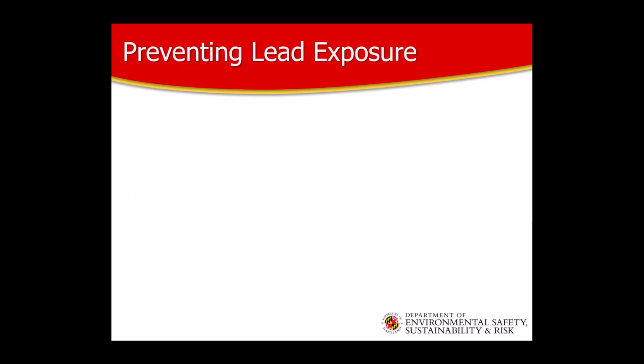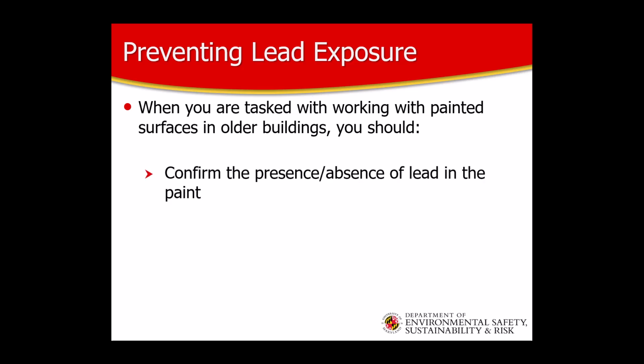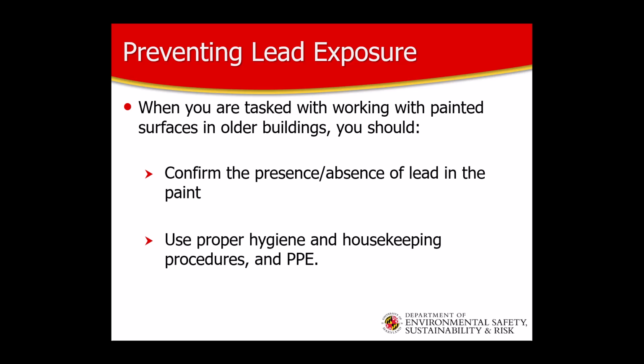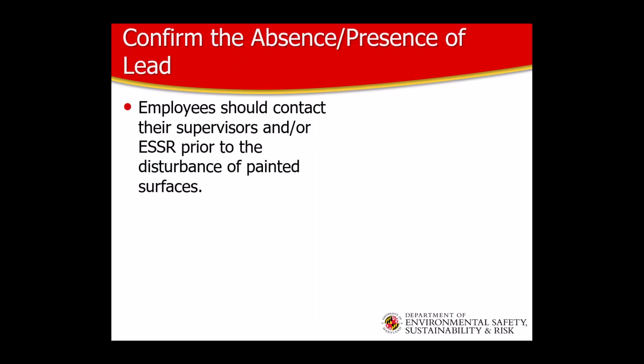Now that we know more about lead and its potentially harmful effects on our bodies, let's discuss some methods of compliance to reduce and/or eliminate our exposure. When you are tasked with working with painted surfaces in older buildings, you should confirm the absence of lead in the paint and always use proper hygiene and housekeeping procedures. PPE may also be necessary. Employees should contact their supervisors and/or ESSR prior to the disturbance of painted surfaces.